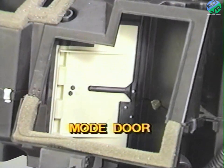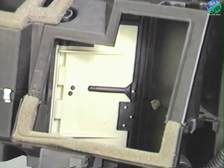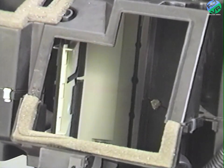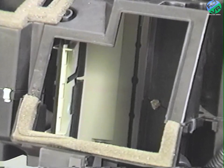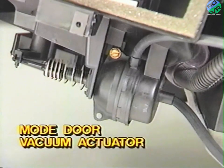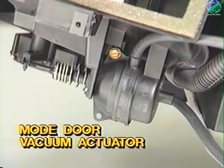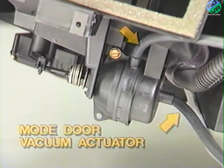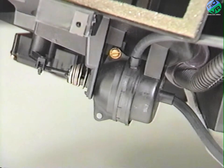The mode door has 3 positions. One directs all air from the air mix door to the heater and defroster outlets. A second splits the air between the heat defrost outlets and panel outlets. A third position routes all air to the panel outlets. The vacuum actuator operating the mode door has 2 vacuum lines connected to it. Both lines must have vacuum to move the door to the panel outlet position.